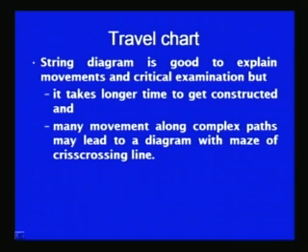Another aspect is that if many movements are taking place along complex paths, then a string diagram may lead to a maze of crisscross lines only. So, the string diagrams are found not very useful if too many movements are taking place along complex paths. Another negative aspect related to the string diagram is that it takes longer time to construct it.